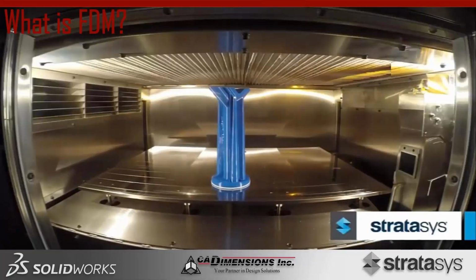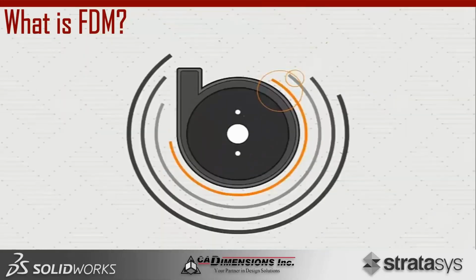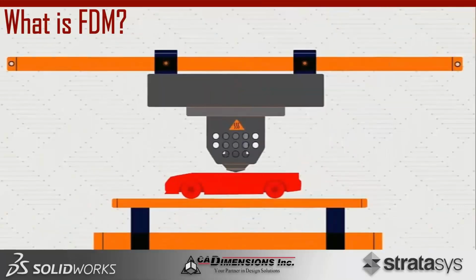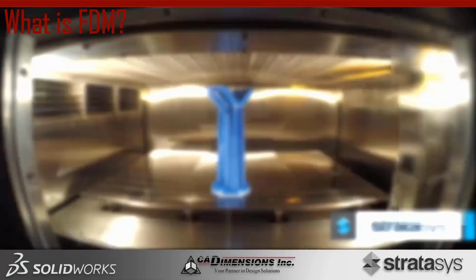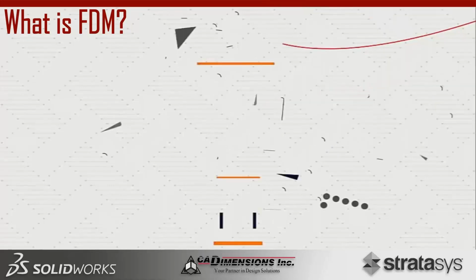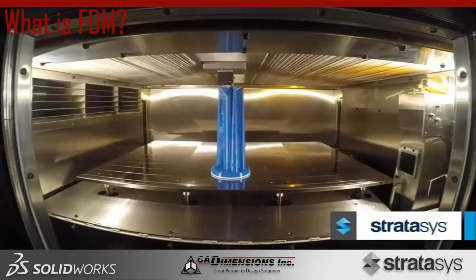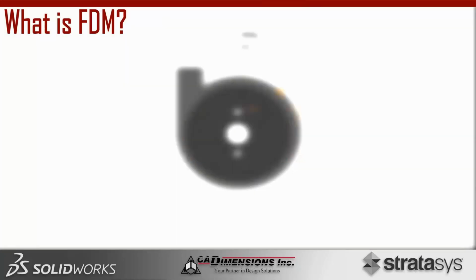So the way this works is it has 2 different spools of what's called a thermoplastic filament. So one is model and one is support. So what it's doing essentially is melting this plastic down, or getting it hot enough to its melting point that it can then be pushed out by the heads to make these structures layer by layer. It will take turns between extruding model material, which is the material that your actual part will be consisting of, and then support material, which is what helps your model be built with different geometries that we mentioned earlier, which can then either be broken off of your model part or be washed away in a soluble support bath.